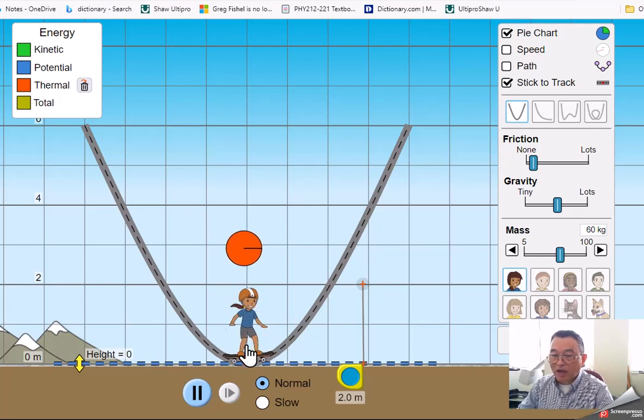What's actually happening is it rubs the surface and makes the molecules move harder, and at the same time the kinetic energy is lost, but the energy never goes away. The molecules or tiny particles in the material on the track or on the wheel get mobilized and move faster, so they become hotter.